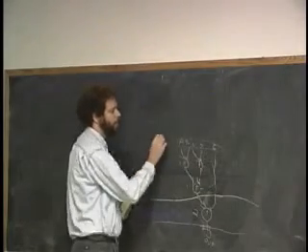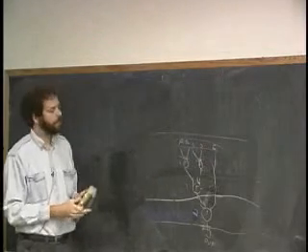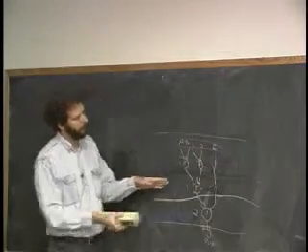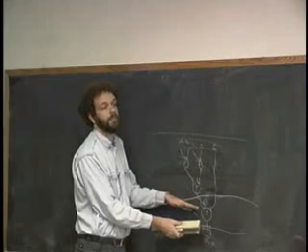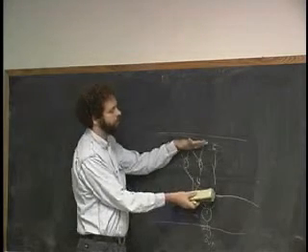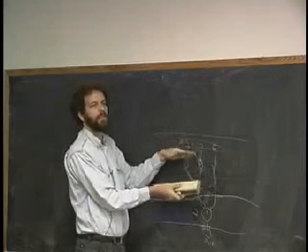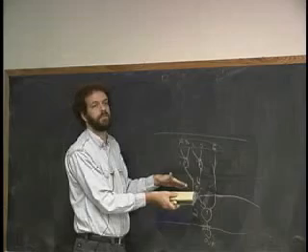Right? And remember, of course, that there's a register on the output of the stage that feeds this thing here. So again, the technique is look for the element that is the slowest, surround it with registers, and then go through the circuit and kind of break up the circuit into sections that have that latency or less.